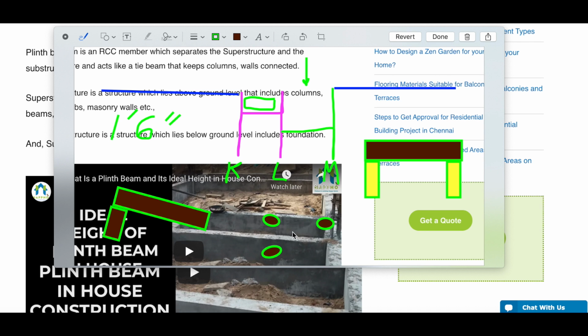Remember, on 611, above 111, she notices cracks in the wall. She takes her time to do all this stuff to leave. That means that at 611, the walls, the front C column, I believe, the C row there, is now separated from the building to some degree. That's where her door won't close, and so we have some loss of engagement of the steel from the pad, which also caused some deflection. But it became stable again for those 7 minutes before it progressively collapsed.